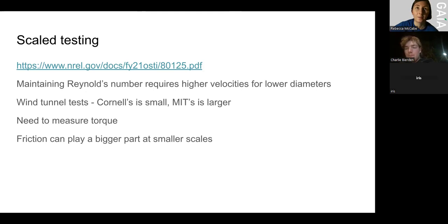And that can definitely affect the results because the amount of lift produced on those blades comes from the pressure difference of the wind going over the airfoil of that specific shape. And if you've now also got the shape of the automobile relatively close to it, there's a boundary layer, there's all sorts of turbulence, just stuff that can mess with it. And so if you want to pursue that, be very careful about it to make sure that any data you collect is not just going to be garbage.